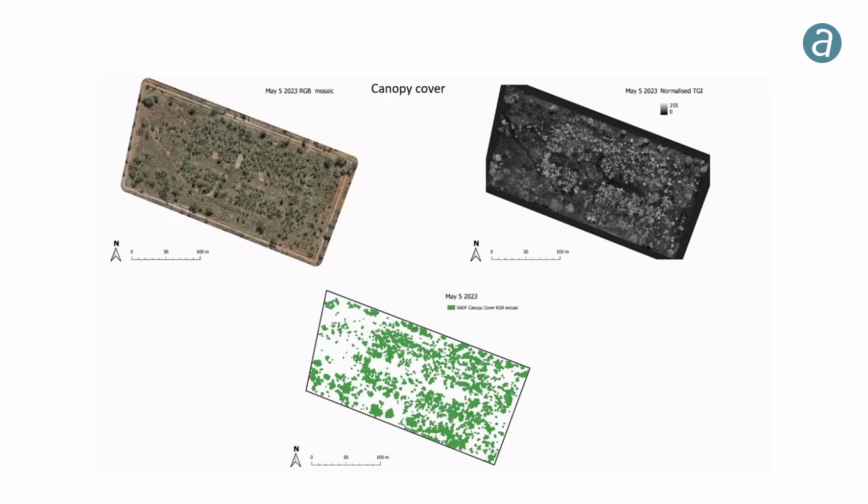You're the scientist, I'm not. One thought I had was, and I know, again, in Correlator3D, it's not our goal to do some of these things. We know our limitations. The one thing I would think is that you could run a DSM and then create a DTM, saving the features that it extracted in creating the DTM, which would be everything above ground, which would also tell you probably what the trees are. If we could detect all the trees in the DSM, yeah, that would be correct. Yeah, but we can't.